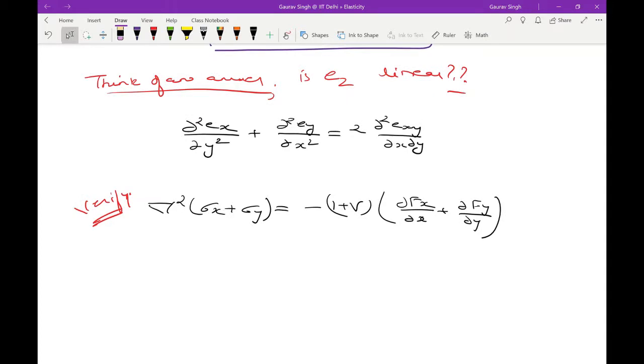Okay, so we have now formulated our two-dimensional region R, and the problem can be formulated for a plane stress approximation. Clearly the unknowns are u, v, εx, εy, εxy, σx, σy, and τxy in R. These are the unknowns, and obviously εz is not separately written because it can be found out by finding εx and εy. That completes the formulation.